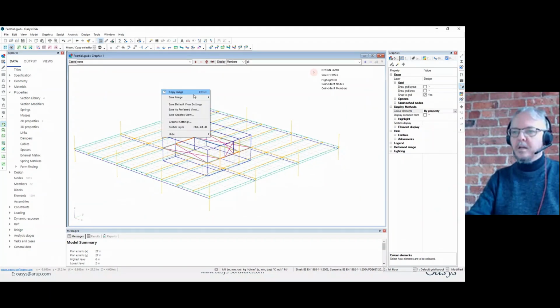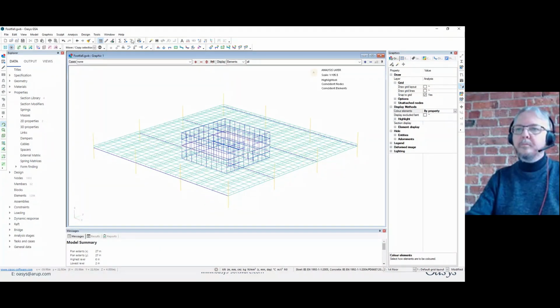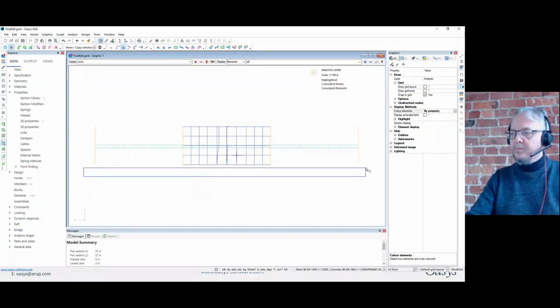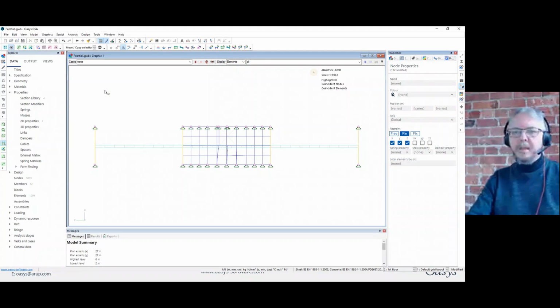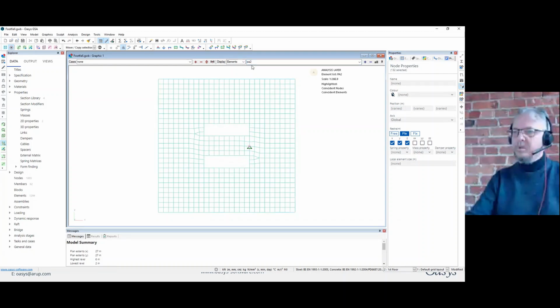Okay, let's switch over to the analysis layer, already meshed. And again, we need some restraints. Now, in the footfall analysis model, we've deliberately not put in end releases on the beams. I will pin the columns and core top and bottom, and then also property area 2.